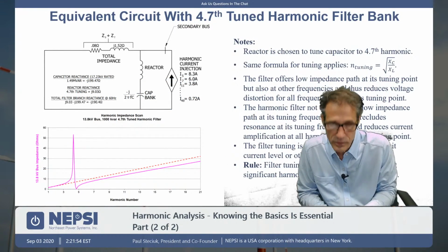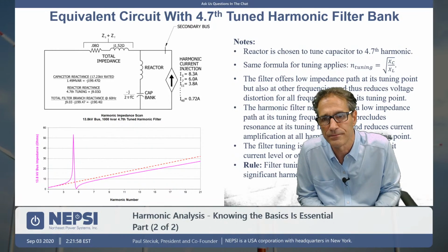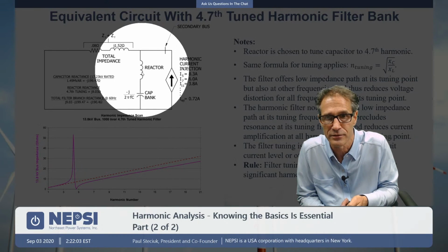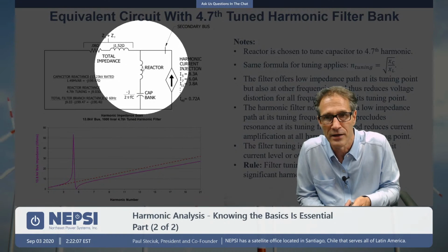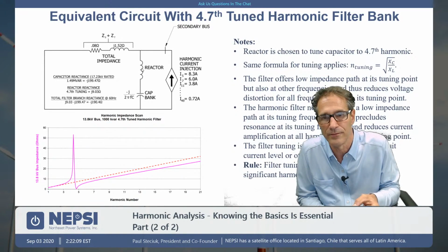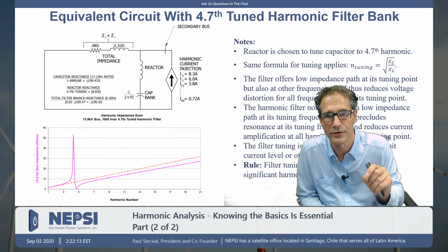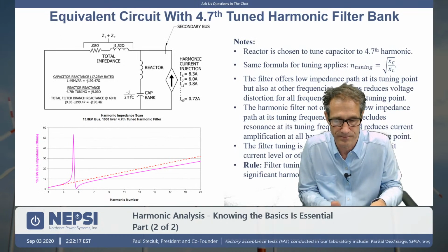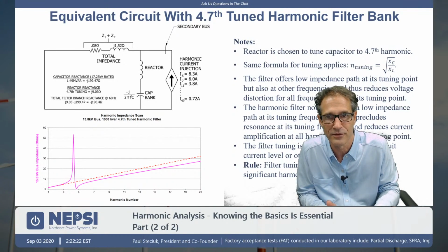So we go back to that system, and we've installed a reactor here, in series with the capacitor. Now that reactor is typically about 1/n² the capacitive reactance of the capacitor. Therefore, at the fundamental frequency, the system is capacitive and it is putting out megavars.